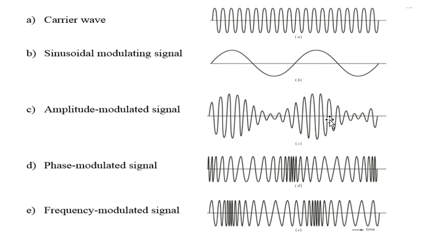And here the other modulation scheme which we are going to discuss in this part is phase modulated signals. You can notice here this is the waveform for the phase modulated signal. We notice the amplitude remains constant, only the corresponding phase or frequency of the waveform is being changed. And you see the frequency modulated signal: it has higher frequency when the modulating signal amplitude is higher, and it has the lowest frequency when this amplitude is the lowest. But it is not easily distinguishable in the case of tone modulation whether it's an amplitude modulated, phase modulated or frequency modulated signal.